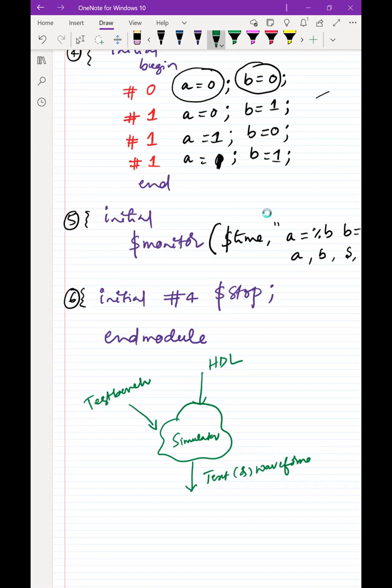So this is the first step you have to do in your design. First we have to describe, second we have to simulate your design. Is it clear to all of you? In the FPGA design process, the first step is to describe the digital circuit. We describe the test vectors we need, and we simulate that. Once the simulation results are correct, then we go to the next step.